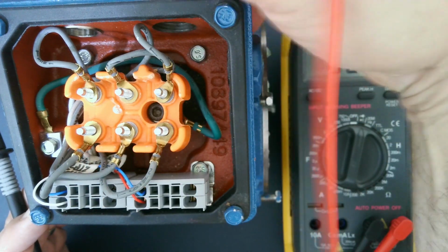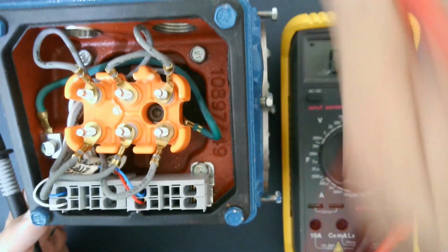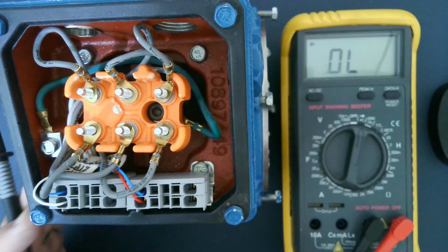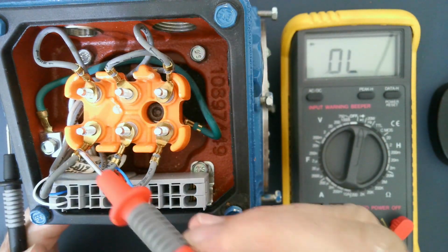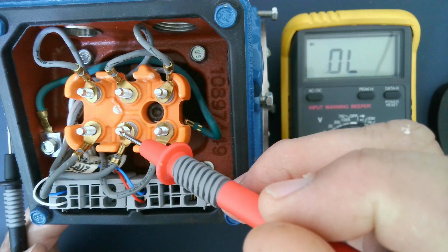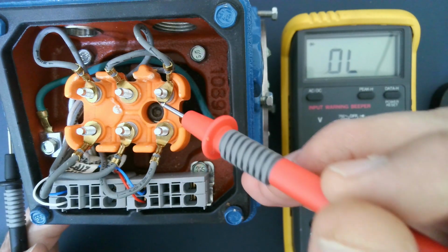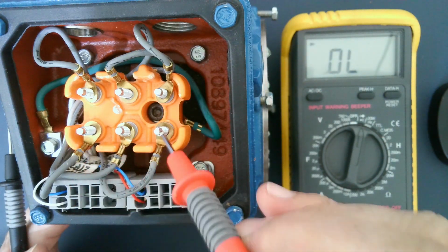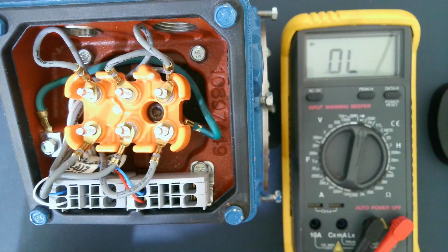We're going to take one of these points, take that one away, and then take the wires connected to the supply. If you would like to connect it as a delta, we are going to connect this point to this point, start to finish, and feed the machine U, V, W. That one is as per the nameplate diagram.